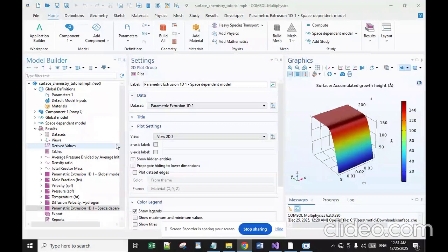And the next one is laser chemical vapor deposition. This CVD process uses a laser to hit spots or lines on a substrate in semiconductor applications. In MEMS and in fiber production, the lasers are used to rapidly break down the precursors. Gas process temperature can exceed 2000 degrees centigrade to build up a solid structure in much the same way as laser sintering based three-dimensional printers build up solids from powders.